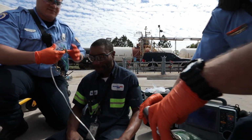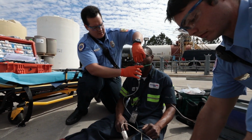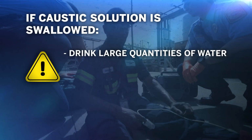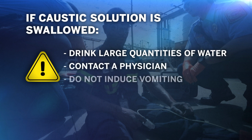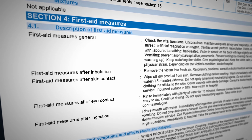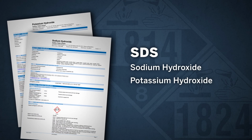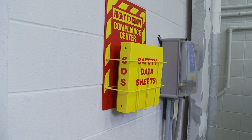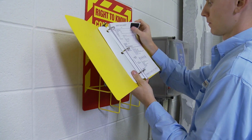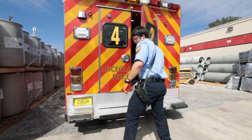In the case of caustic mists or aerosol inhalation, quickly move the victim into fresh air and consult medical personnel. If caustic is accidentally swallowed, drink large quantities of water and contact a physician. Do not induce vomiting. Much of the information presented here is contained in the Safety Data Sheet, more commonly known as an SDS. This sheet is available from the sodium hydroxide or potassium hydroxide supplier and should be studied and understood. Keep a copy readily available for review. It's also valuable to send a copy of the SDS with the victim when transported, as a quick reference for medical personnel.